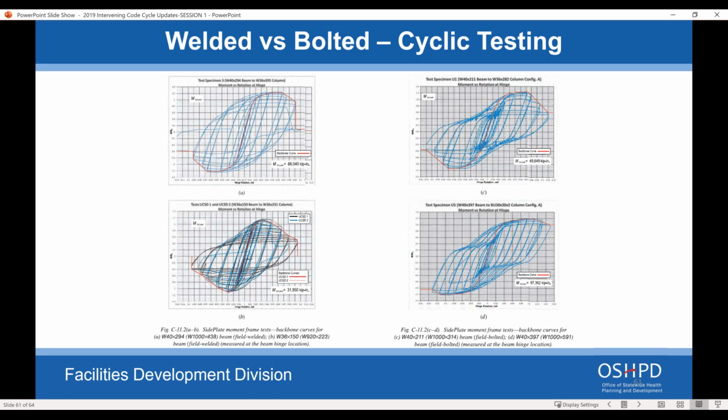However, when it comes to things like wind, we want to stay within a certain range. For events that are supposed to be elastic, that do not push your deformation into the inelastic range or for a required R factor, we will limit your Mp to a fraction of the moment capacity of the beam for wind design, but for earthquakes, we will permit you your full capacity. Looking at all those, we came up with the design criteria. Can you go to the next slide? So we came up with some design criteria for that.